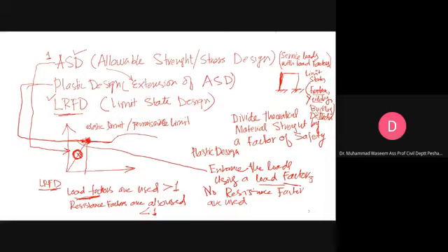Okay. Now we know that whenever we design our building, the building lifetime is 50 years. And in the 50 years, you have to consider the maximum effect of loads. If you are considering the maximum effect of one dead load, it should be coupled with the live load, it may be coupled with the snow load. Okay, so these loads actually produce some limit states. These are fracture, yielding, buckling. Okay, now in ASD or in the plastic design approach, we do not use any resistance factor.